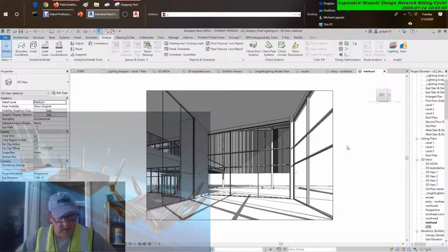Now, conceptual massing analysis. Conceptual or massing analysis allows you to analyze the energy consumption of the model directly within Revit. Using this workflow, you analyze mass forms in the model and view energy simulation results with insight, guiding early-stage architectural decisions such as geometry, orientation, window-to-wall ratio, shading, and materials to reduce energy consumption.